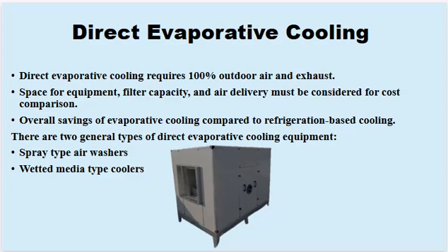Direct evaporative cooling pulls 100% outdoor air into the system. The air is cooled by coming into direct contact with water as it evaporates. This cooled air is then sent indoors, creating a comfortable environment. To maintain balance, the system uses simultaneous air exhaust to regulate airflow.